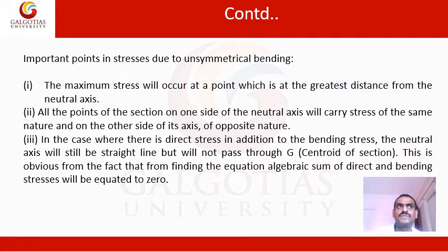The center of the beam will have the neutral axis and neutral plane. The portions above the neutral plane, towards the bending, will be subjected to compressive stresses. The portion of the beam away from the neutral axis, that is the outside portion, will be subjected to tensile stresses.